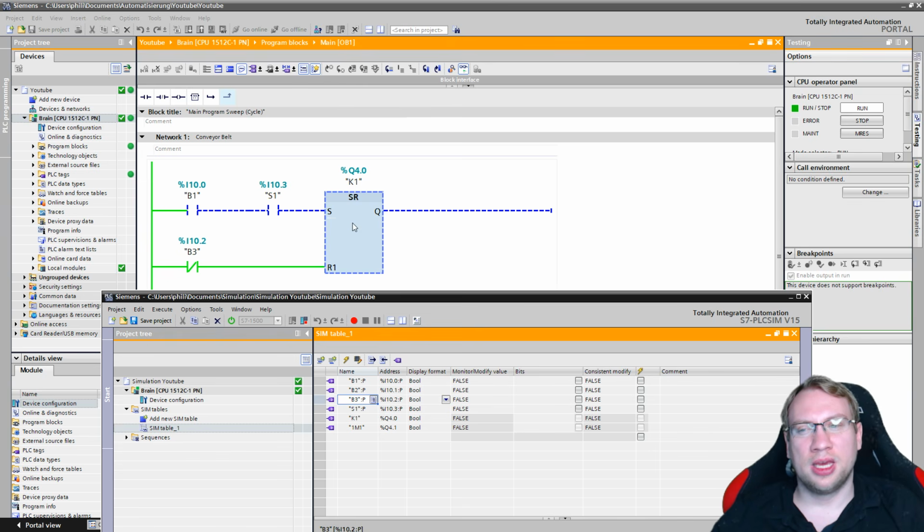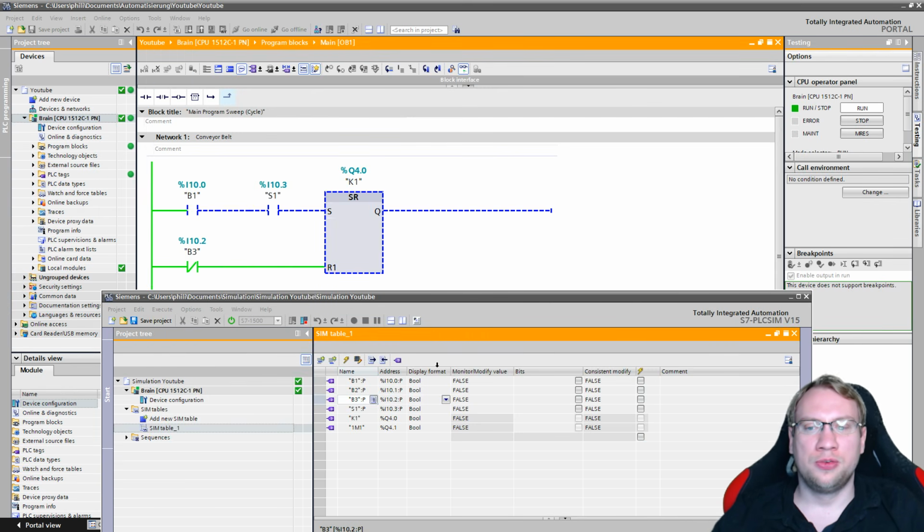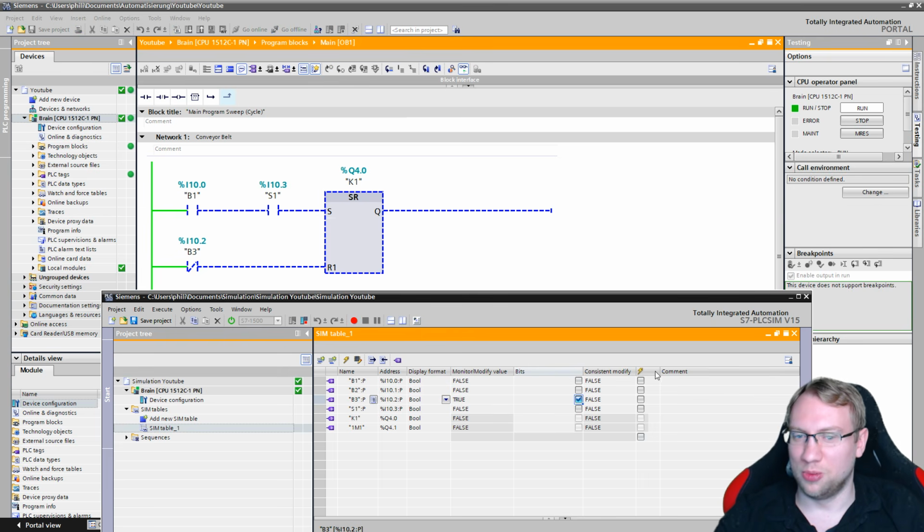To turn on K1 here, what do we need to do? First thing, B3, right? B3 is the first thing. B3 is actually always sending a high signal if there's no component, so I will activate it. You can see in the background, here, the green path turns off, because now we have a 1 here. 1 here means this will open, not letting any path through, electrically open.